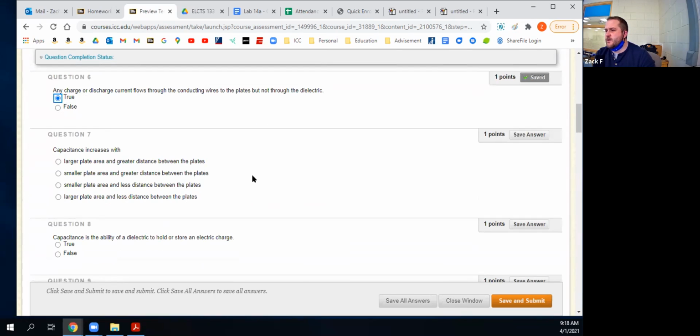Capacitance increases with which one? Right. So that's the example that I just gave. I have 2 capacitors I build the same way, but with one of them, I increase the size of the plate and I move the distance. If I make that plate thinner, so the distance between the 2 conductors is shorter, then I increase the capacitance. It's able to store more charge.